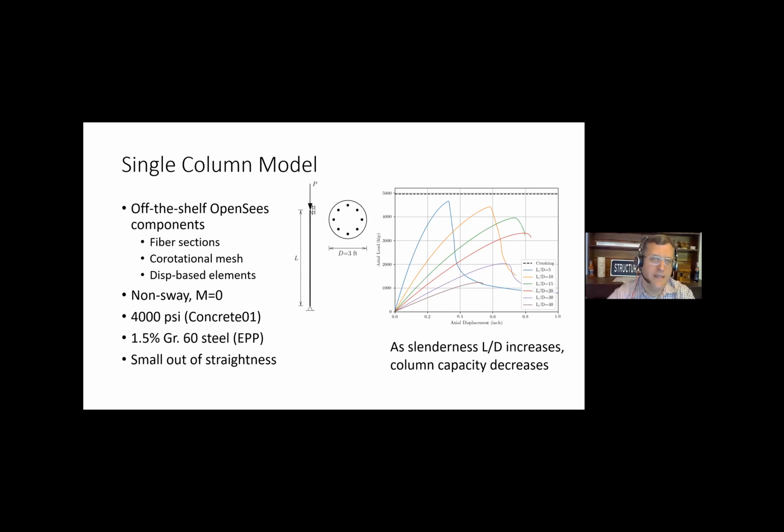Mark and I met with Sharon on Friday, and we told her we could do an easy off-the-shelf OpenSees analysis in a couple hours. So I did that this weekend and ran some OpenSees analyses with circular reinforced concrete columns, just to show you what types of analyses we're thinking of, initially with off-the-shelf components like fiber sections and a co-rotational mesh of displacement-based elements.